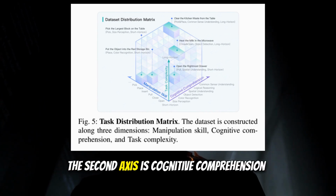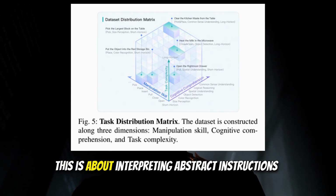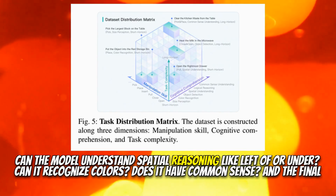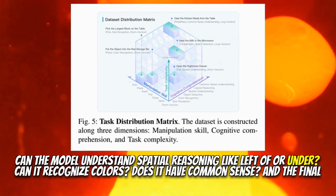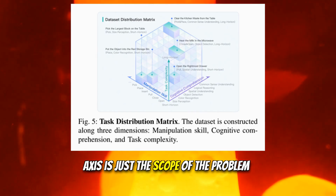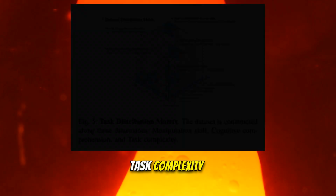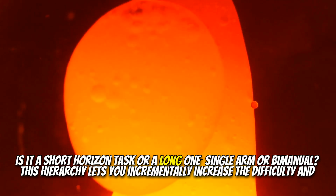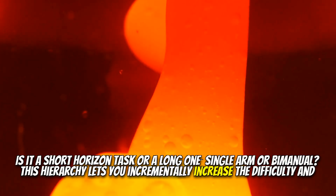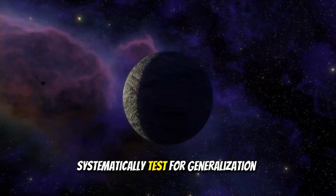The second axis is cognitive comprehension. This is about interpreting abstract instructions. Can the model understand spatial reasoning like left of or under? Can it recognize colors? Does it have common sense? And the final axis is just the scope of the problem. Exactly. Task complexity. Is it a short horizon task or a long one? Single arm or bimanual? This hierarchy lets you incrementally increase the difficulty and systematically test for generalization.